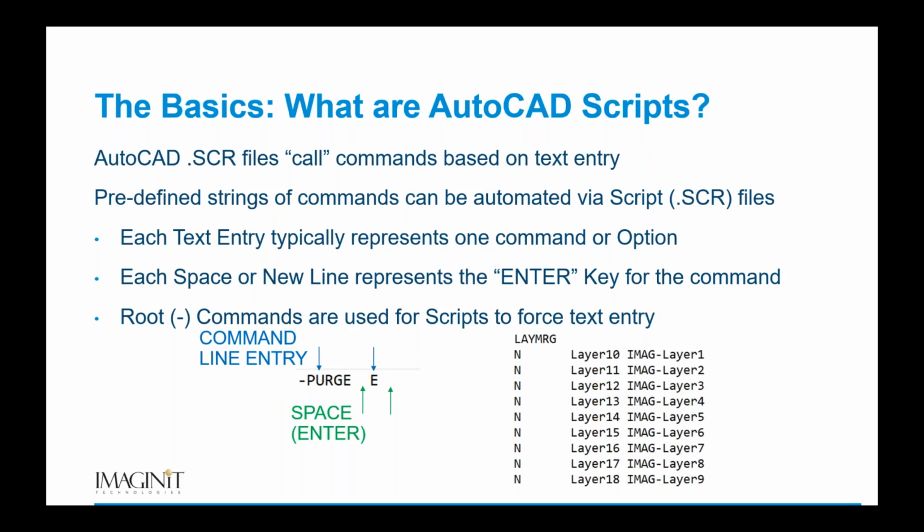And when we're running scripts, because we are focused all on command line entry, that's really the key for what we are shooting for. So we're going to do a lot of command line entry, and in cases where there are dialog boxes by default with standard commands, we're going to try and trigger the root command by adding that dash symbol before the standard command is typed in, so that everything is command line driven versus the dialog box.